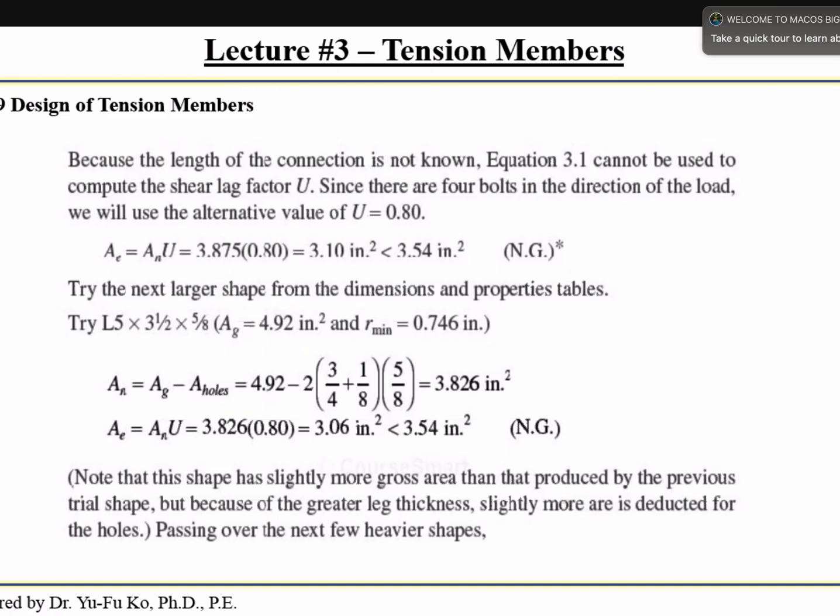You are looking for the r about the axis ZZ, not about axis XX and YY. There are 3 r values if you look at the manual, one under XX, one under YY, and another one under ZZ. You need to pick the one under the ZZ axis. Okay, so we're always choosing the one under ZZ. That's for an unsymmetric section.